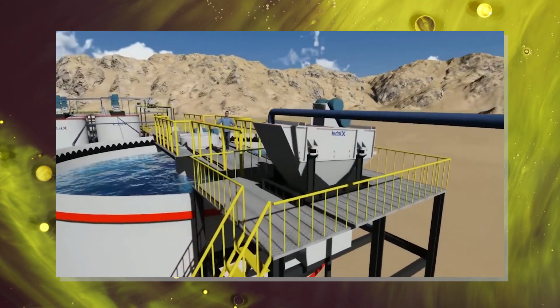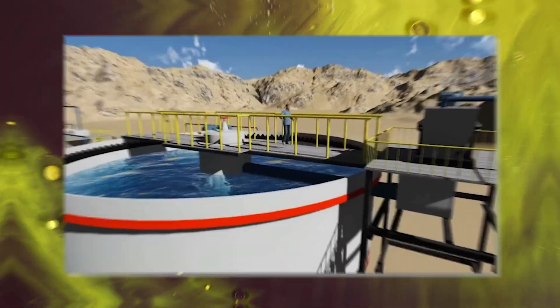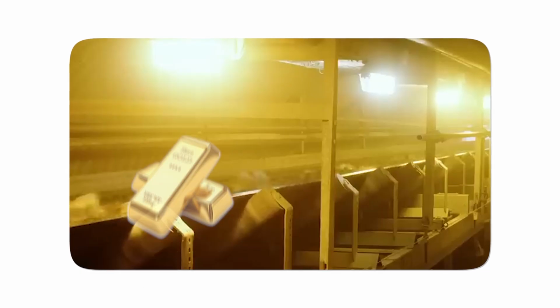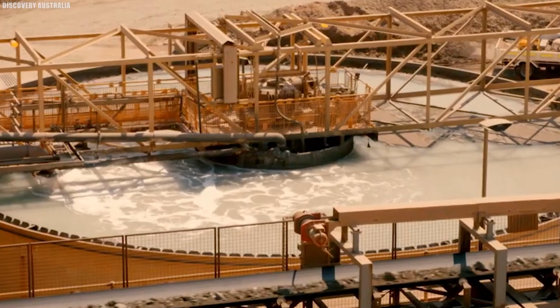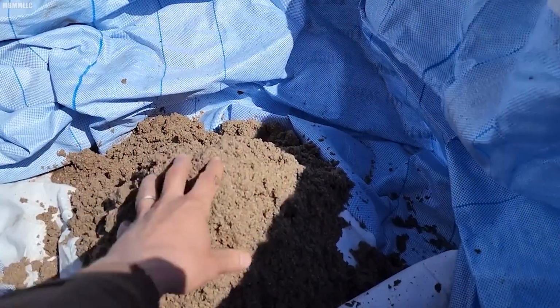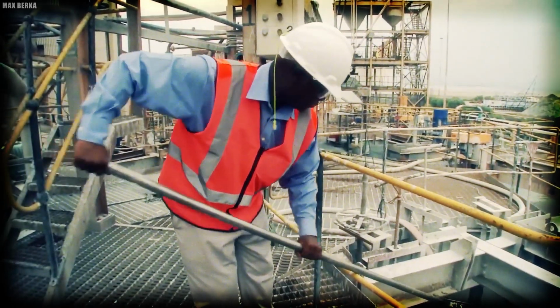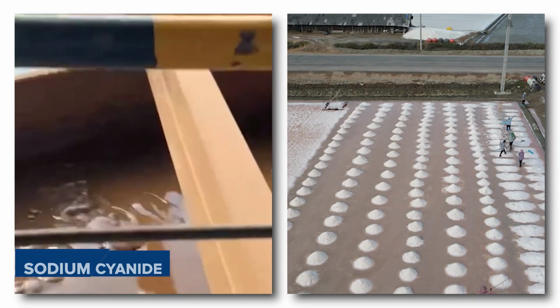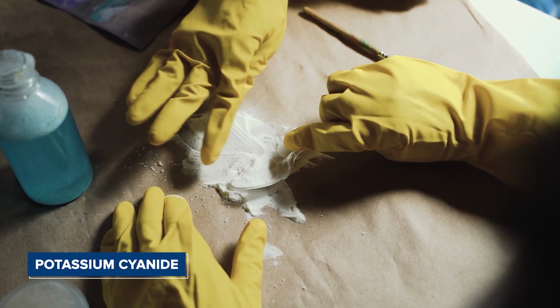Cyanidation is essentially a hydrometallurgical technique where cyanide solutions are used to extract precious metals like gold and silver from their ores. Here's how this intricate process works. The ore is first ground into a fine powder, creating a larger surface area for the cyanide to act upon. This powdered ore is then mixed with water and a solution of sodium cyanide or potassium cyanide.